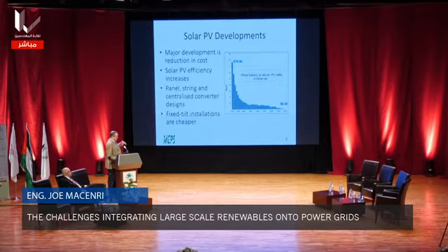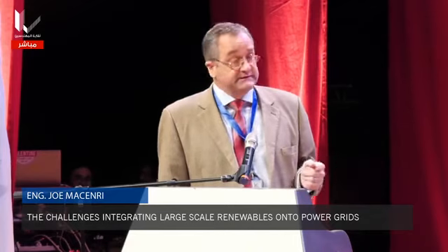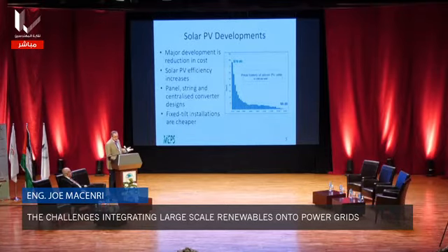With the solar PV, to get maximum energy output, you generally have to have 2 axes tilting for the maximum output. So you're following the sun for both seasonal and the daily sun. But that tends to be quite expensive, so a lot in the earlier days tended to go for a single axis, which was following the sunlight throughout the season. However, the fixed tilt is becoming increasingly popular because the energy loss is small, and it was fixed tilt in the one that we saw there on the front, in the first slide. It's cheaper and the maintenance costs are easier and significantly lower. So increasingly, these large-scale, grid-scale solar PV farms are fixed tilt.